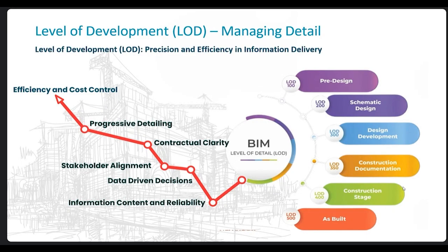Once they hand over the model, once the building is in operational phase, only then will we submit the as-built model, in 90% of scenarios. If you submit earlier and some changes are later implemented on site, those changes need to be reflected in the model in the later phase of the process.